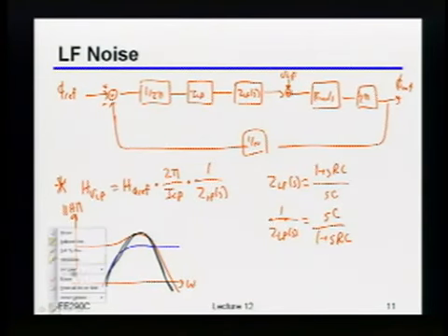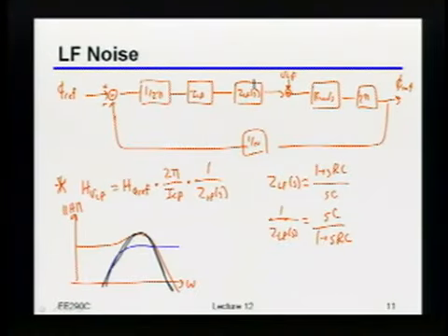Okay, so now, keep this in mind, or hopefully maybe you guys have seen this before. We've just said that if I add noise onto the loop filter control voltage, then that's going to go through the loop and be bandpassed to the output. And the reason it's bandpassed is that if I've got an integration in front of it, any noise at DC basically doesn't matter. You throw that out.